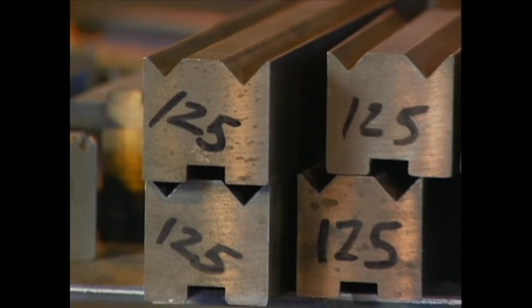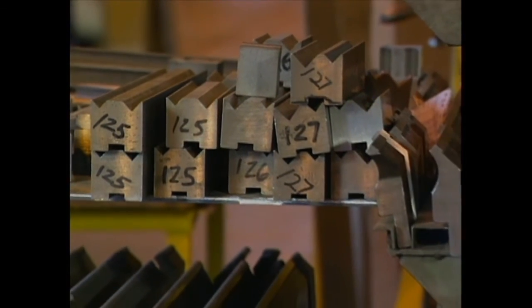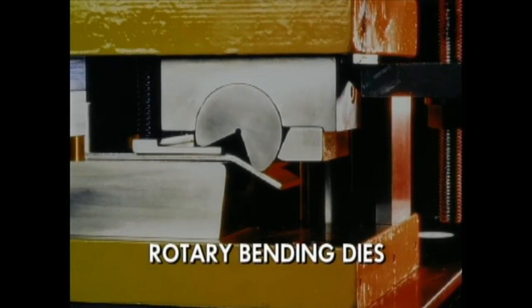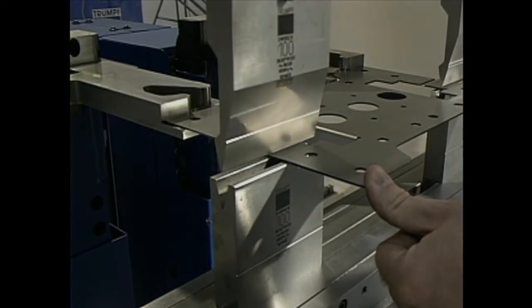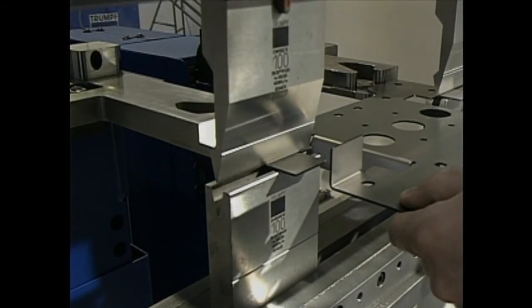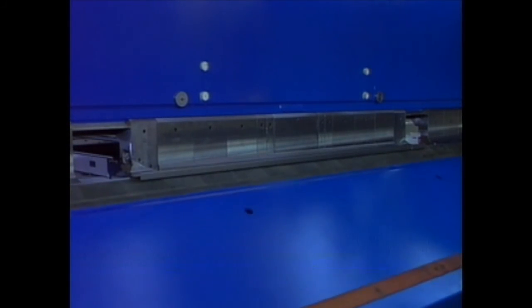90-degree V-shaped dies are the most common type of bending die, but many other types are used to produce shapes, such as acute angle dies, gooseneck dies, offset dies, and rotary bending dies. The addition of computer-controlled gauges to press brakes has greatly extended their accuracy and made possible the economical production of multiple bend, multiple stroke parts in a single setup. The folding machine is also used in bending and is especially suitable for large or complex parts requiring multiple bends.